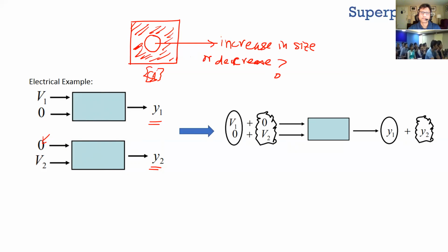So basically you take a metal plate, you cut it, and you heat the plate. The question was, will it increase or decrease? And you're supposed to use the superposition principle, but there is one assumption you have to make, and I'll tell you what that assumption is. You assume that this heating of the plate is actually a linear function. In other words, everything happens linearly. For example, the plate will expand linearly, the hole will expand linearly, whatever it is, but it's linear. That's the only way you can apply the superposition principle, okay? So think about it.